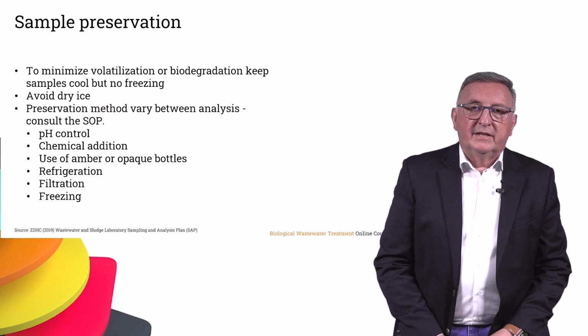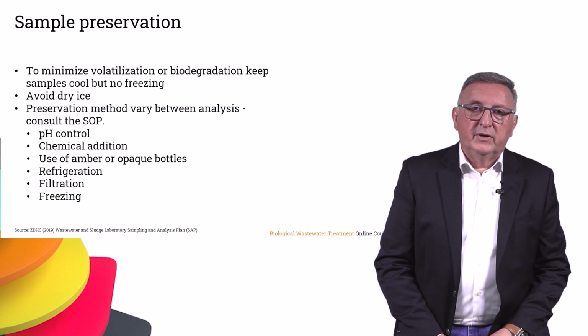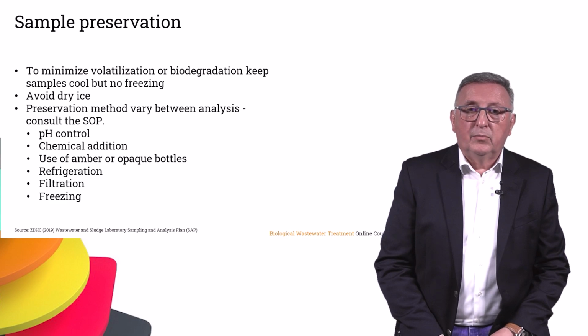To minimize volatilization or biodegradation, keep samples cool but not freezing. Avoid the use of dry ice. Preservation methods vary between analyses, so you need to closely consult the standard operating practices concerning pH control, chemical addition, use of amber or opaque bottles, refrigerating, filtering, and freezing samples.